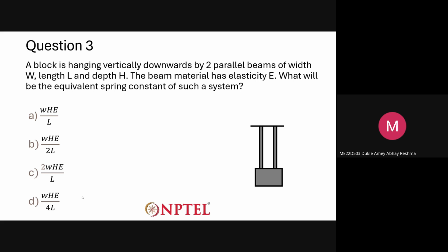So when the deflection is the same, you add the spring constants. For the electronics guys to remember, when you have resistances in series, you add the two resistances. In the same way, when you have springs in parallel, you add the spring constants, and when you have springs in series, use the parallel equation.